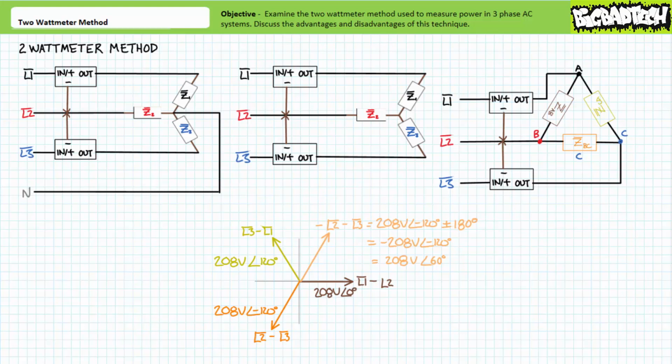Note both wattmeters in the 2 wattmeter method are external to the Y or delta configured load and do not necessitate any invasive inspection. If the thought, each wattmeter in the system is reading nonsense, ever crossed your mind, you'd be absolutely correct. In isolation, each wattmeter's reading in the 2 wattmeter method is absolute garbage. If, however, we add the 2 wattmeters' readings, we obtain the total apparent, the total real, and the total reactive power. How can this be true?